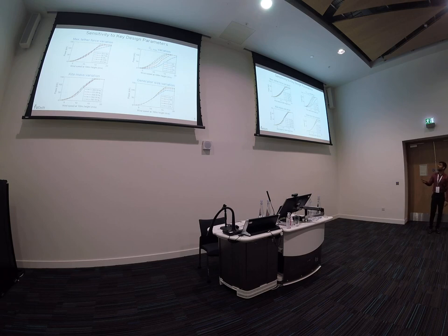And this is the variation with the maximum tether force, so basically how strong the tether is, and the generator size variation. The blue line, the 2.1, is basically a ratio between the cycle power and the generator size. The generator size which I showed you earlier was 450 kilowatts. But if you use a 300 kilowatt generator, the reel-out power cannot exceed 300 kilowatt, and hence the cycle average in the end cannot be more than around 130 kilowatts.